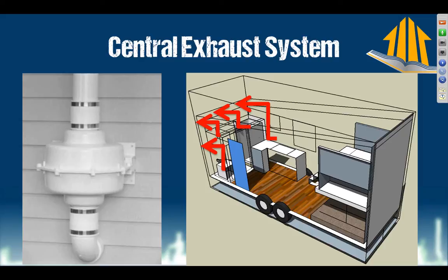But basically, we're going to take a whole bunch of little pipes, the diameter depending on how much air I want to suck from each individual area. The toilet and the litter box, a very, very small amount of air. All I need is air moving in the general area, in the direction of away. We want everything flowing away when it has to do with smells. Likewise with the shower and the kitchen. We don't need a whole lot if I can get it going in the right direction.